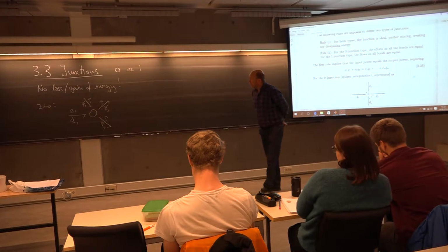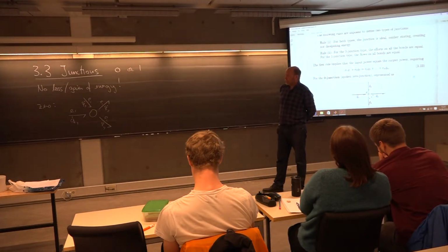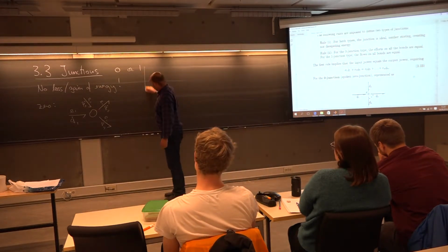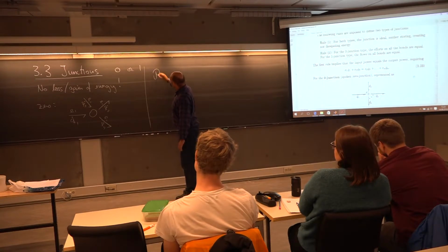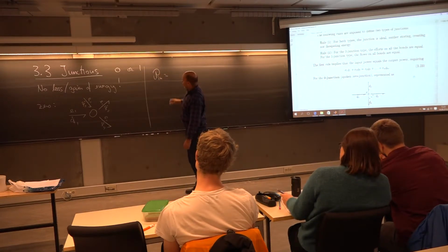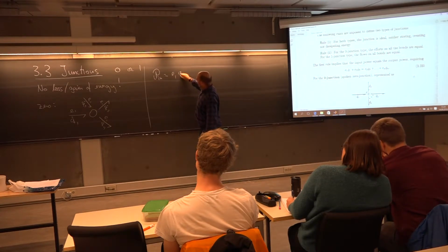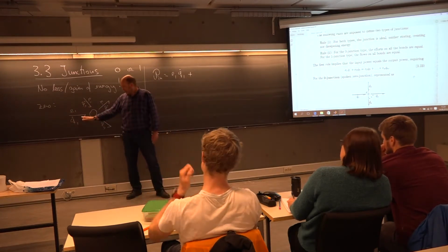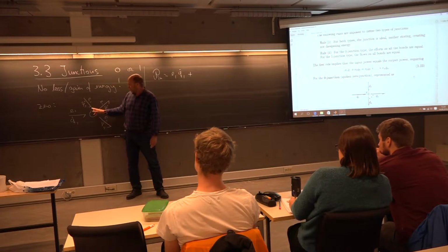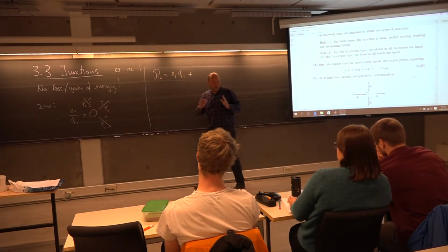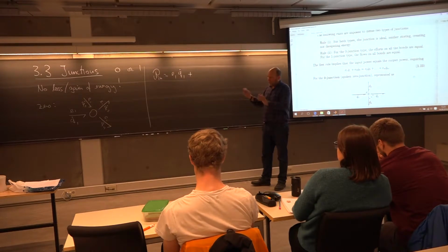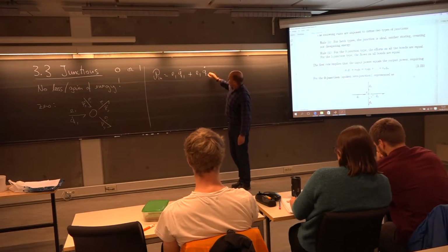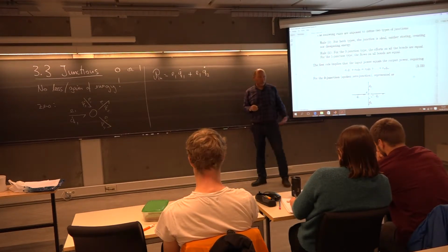And now, if you look at the power that comes in, power in will be E1 times Q dot 1, that's the power from bond 1 in watt, plus the second one, which also goes in. Here, the direction of these half arrows tells in or out. The effort is the same, but the flow is now number 2. That's what comes in.